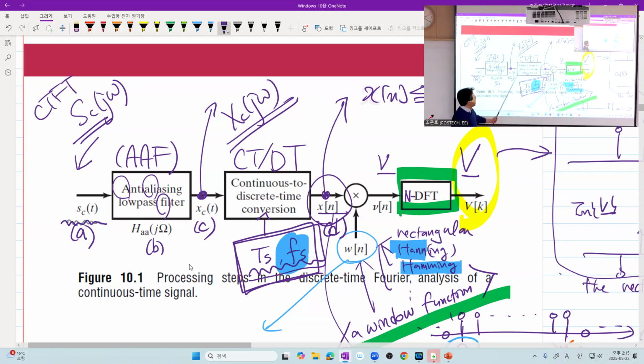Be careful. Inside this one, you have a multiplier that multiplies a periodic impulse train to the input signal, right? So if you delay the signal, then this signal is not just delayed. It's sampled at slightly offset sampling instances, and unless the signal is constant or very special, you don't have time invariance. So this is a linear system.